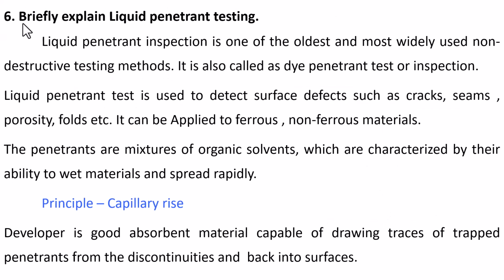Sixth question: briefly explain the liquid penetrant test. Liquid penetrant inspection or test is one of the oldest and most widely used non-destructive testing methods. It is also called the dye penetrant test or dye penetrant inspection. It is used to detect surface defects such as cracks, seams, porosity, folds, etc. Generally, it is used to find cracks in the surface of the material. It can be applied to ferrous and non-ferrous materials.